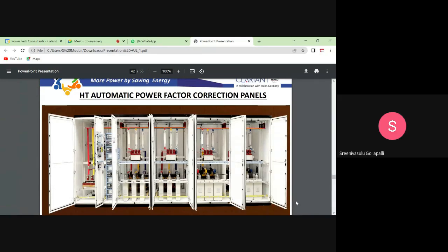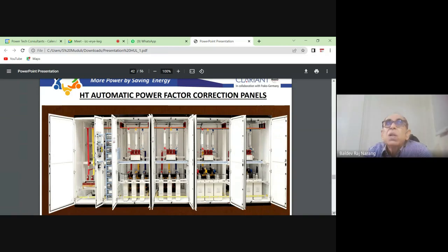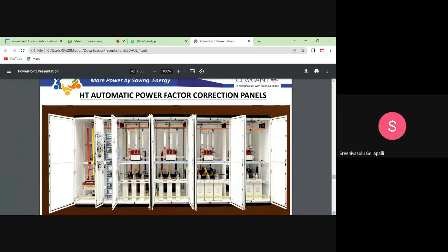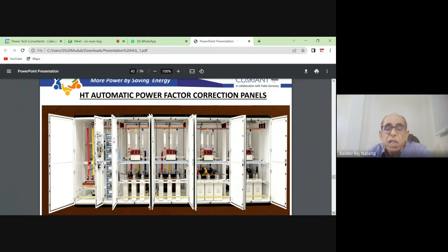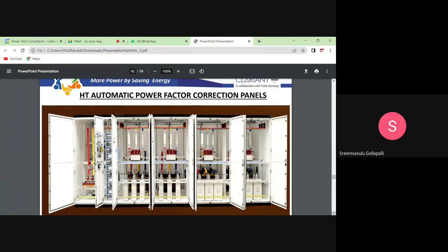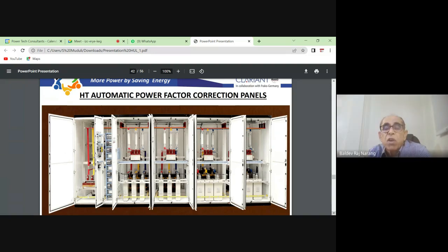So how can we consider harmonics, and what is the procedure to mitigate the harmonics? Here it is the same. Although the soft starter is not in the picture throughout the load, it is only during starting. Yes, sir. If the starting is not very severe, we can ignore it. If it is a severe problem, if the harmonics are creating issues, then the same filters we have for passive and active, whether full-time or part-time, the job is the same.